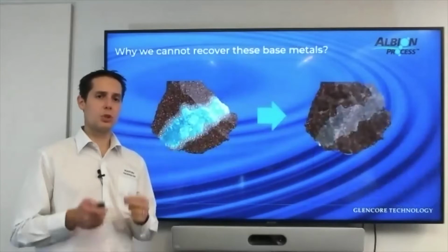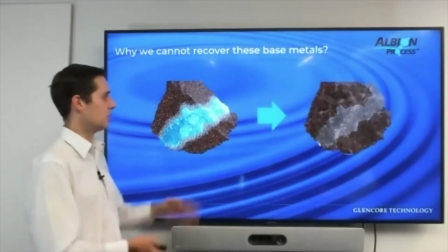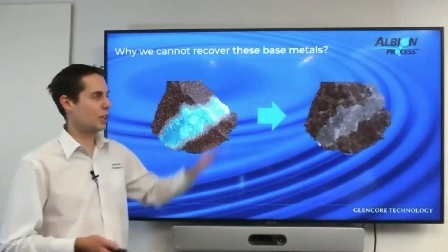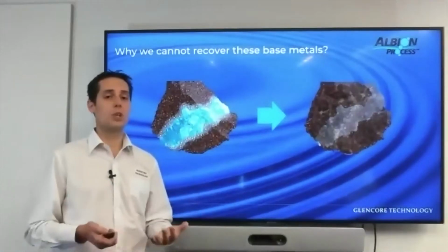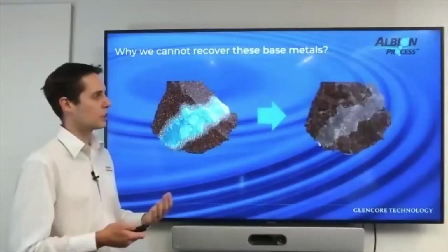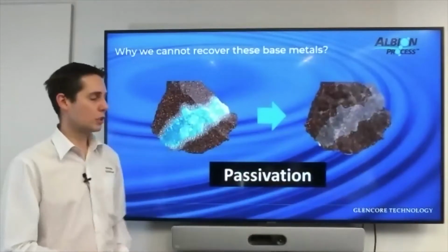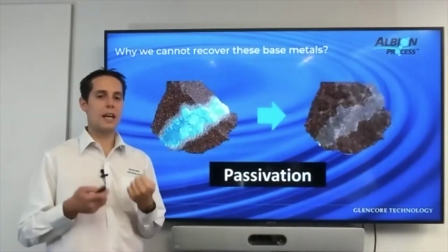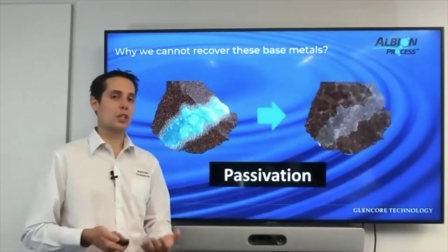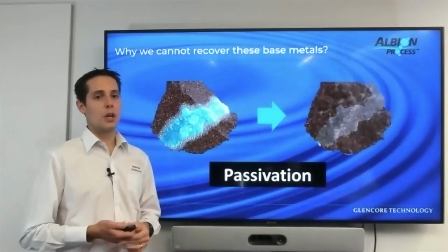But before we get there, we should really talk about, well, why is it that you can't recover these base metals? In this simple diagram that we have up here, our base metals are this blue mineralization that you see here. Why is it that we can't recover it? If you put it through this acidic leaching process, what happens to these sulfides is that they start to form what is known as a passivation layer. So you're not actually able to get more acid in contact with the fresh base metal to be able to then extract it into solution.